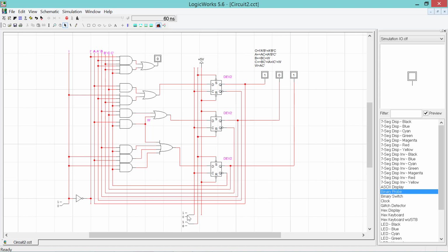Every time we have a 0 or a 1, we count down. It should count down until we hit state 0, and then when we hit state 0, we should see an alarm. And then when we reset the alarm, we'll see a 0 on the output again. So let's clock. Go down from 5 to 4, 3, watching this, state 2, state 1, state 0, and we've seen the alarm. So we clock to state 0, and we are cycling.